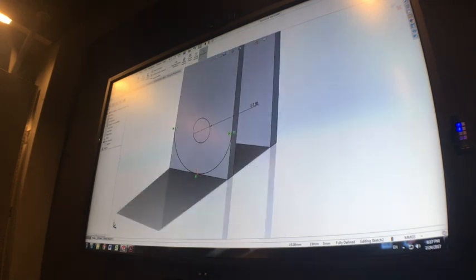So, what I'm going to do now is an extruded cut. Now this sketch is a little bit different because we've got one closed space here, which is inside that circle, but then we've just got a line here on the outside. The difference is, it comes up with this box down here, selected contours. We need to select which areas we're going to cut away.